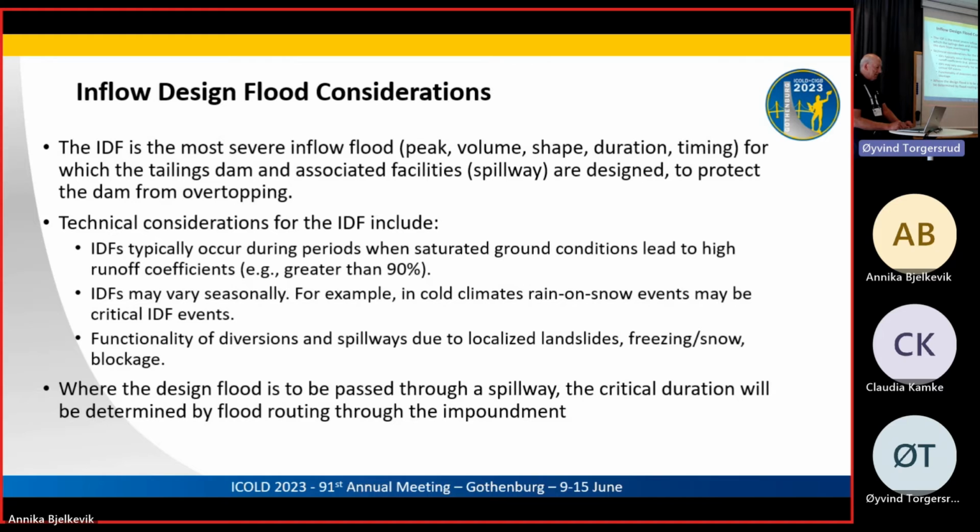Okay, I don't want to get into talking about PMFs if I can help it, but we need to consider that when inflow design floods are occurring, it's going to be at a time when the ground is saturated. So typically we use a runoff coefficient of 1 if we are trying to calculate floods. I don't know if Malcolm's going to put his hand up about that, but also things like rain on snow events.